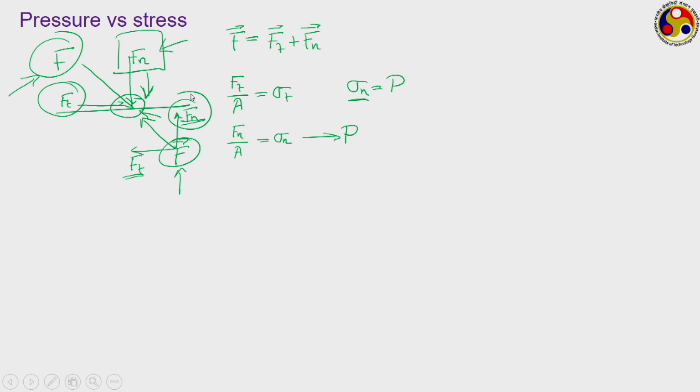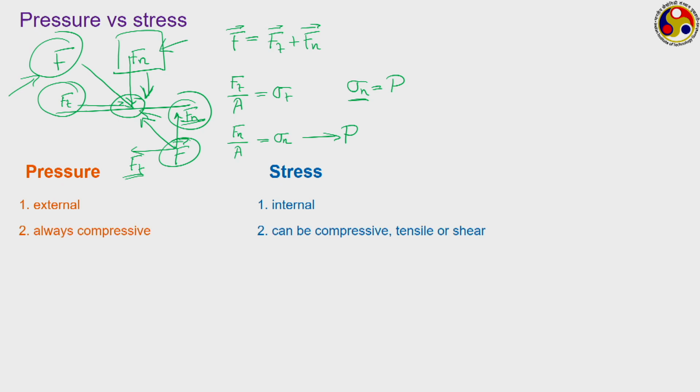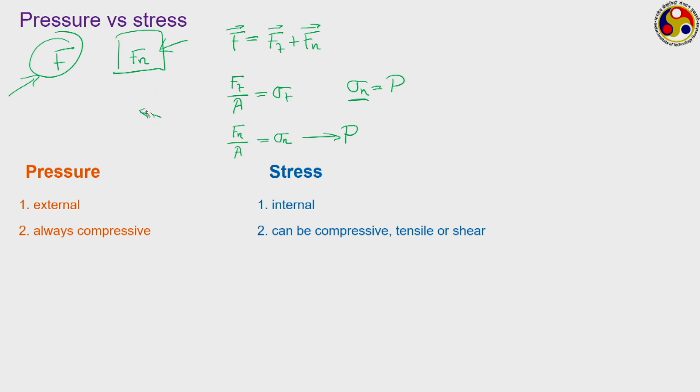So, if we try to compare force and pressure, then of course, just as I mentioned, pressure refers to the external force, whereas stress is generated because of the internal forces developed within the body to resist any kind of deformation. Pressure is always compressive in nature. That is, if the force is acting this way, that is into the surface, then pressure will correspond to its normal counterpart.